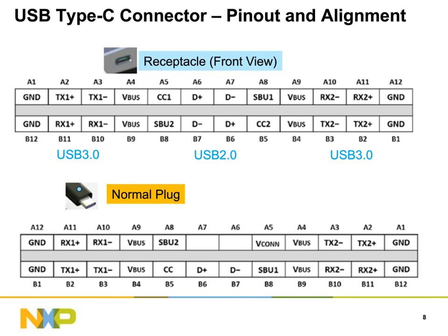Those are the high-speed lanes capable of taking 20 gigabit per second data traffic through them. So through those pins, you can send your USB 3 or USB 3.1 signals, and your alternate mode signals would also pass through the same pins.